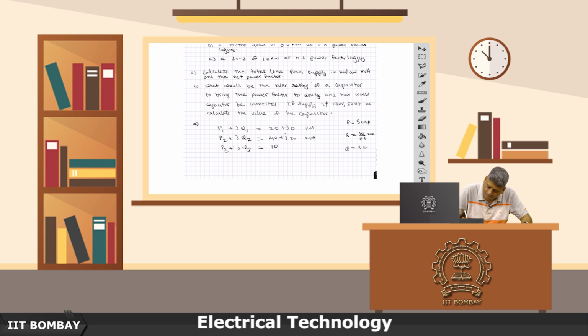S sin phi, will become 10 divided by 0.6 into sin phi. If cos phi is 0.6, then the sin phi will be 0.8, and so therefore 10 divided by 0.6 times 0.8, which is 40 by 3, or 40 by 3 is going to be 13.33 kVA.